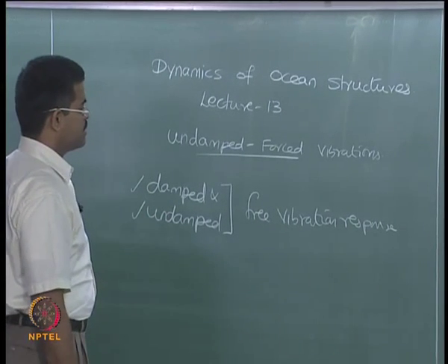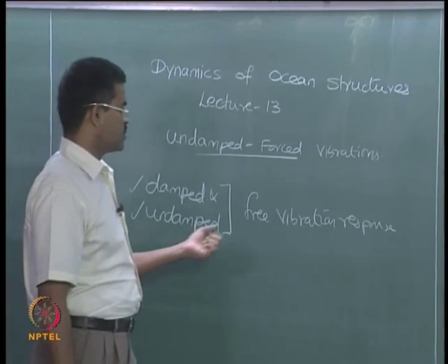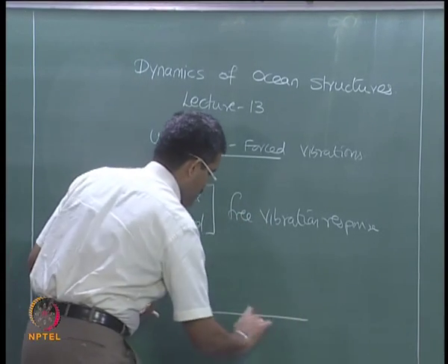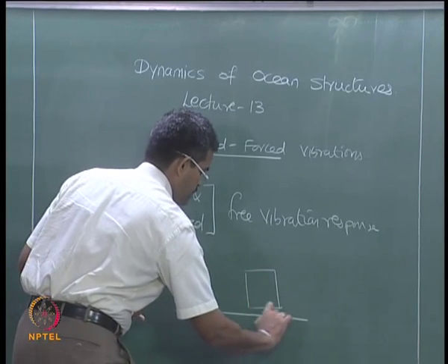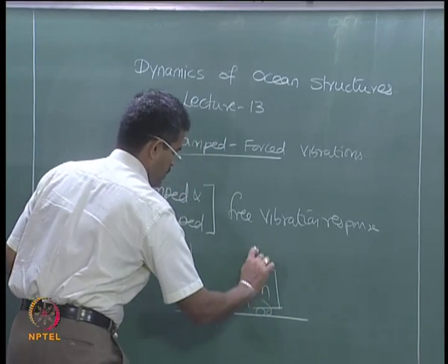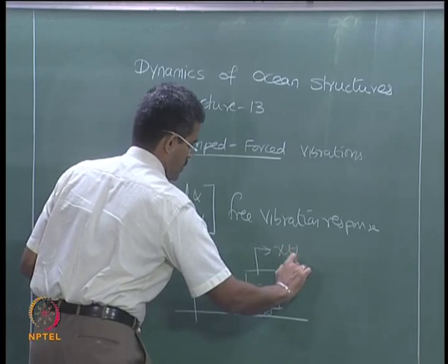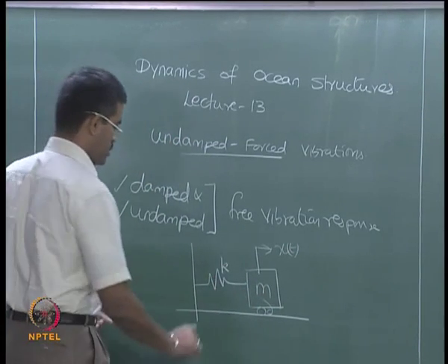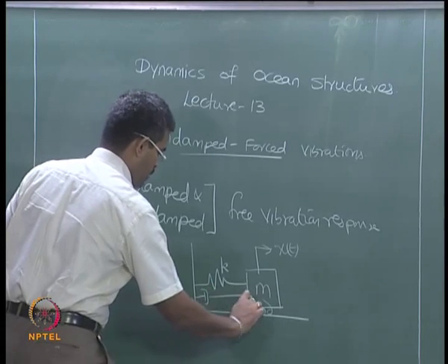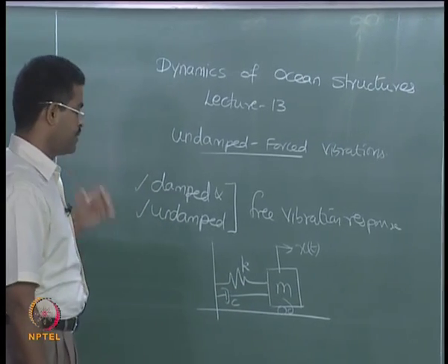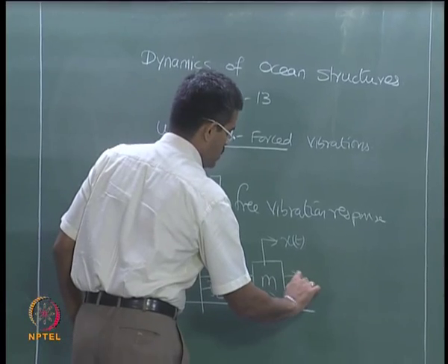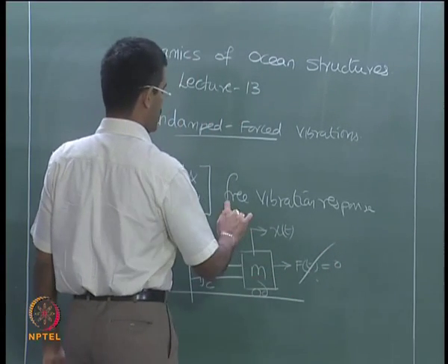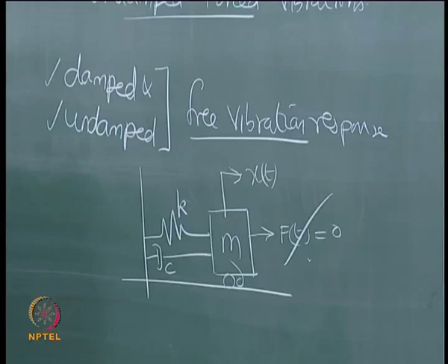So we already said when there is no excitation force happening to the given system, let us say you have a simple single degree of freedom system model, you have the elastic restoring force always present in the system, you may or may not have C present in the system, and of course f of t is set to 0. That is why we say it is free vibration analysis or free vibration response.